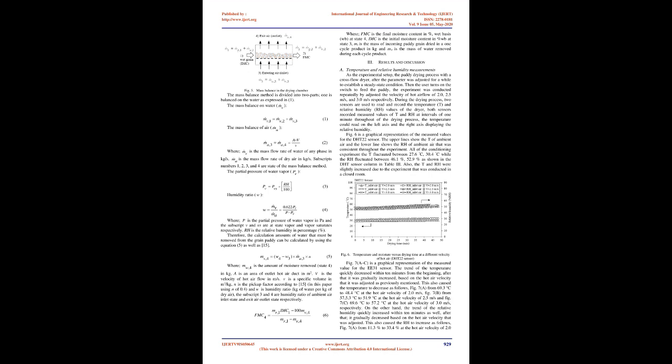Temperature and relative humidity sensors. The ambient air temperature, T, and humidity, RH, were measured using DHT22 digital temperature and humidity sensors, which the researchers applied [14] to the data logger equipment. The T and RH of the hot air after passing the drying chamber of the cross-flow paddy dryer were measured by an E+E Electronic series EE31 humidity and temperature transmitter.